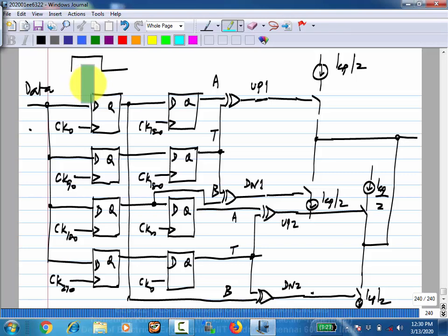But still, for instance, the aperture and the setup time and so on for the flip-flop should be the same, because the data can change in that time, right? But because the clock is elongated by a factor of 2, you do have more time for regeneration. So your latch implementation and these things become better. Because the waveform has a longer period, it can settle better, etc. So some things do become better with this.